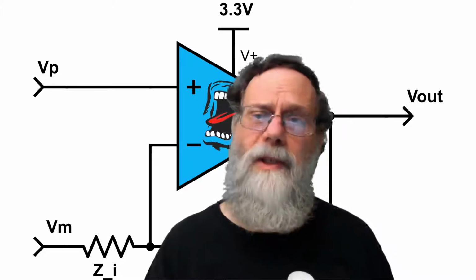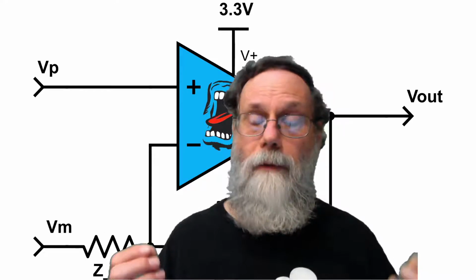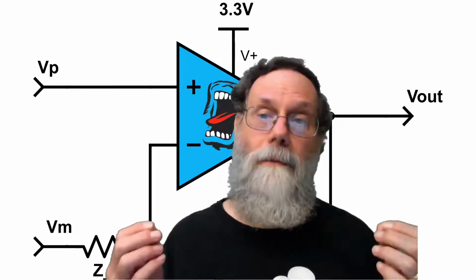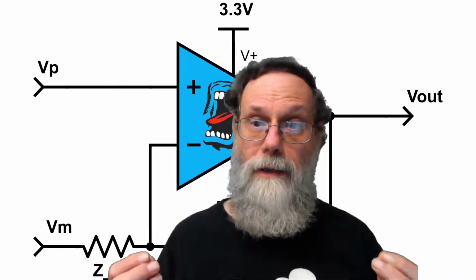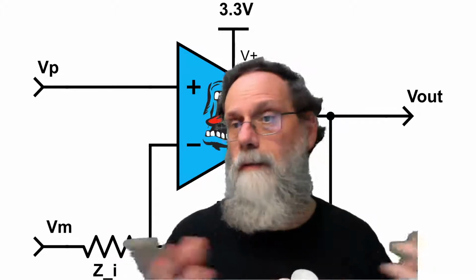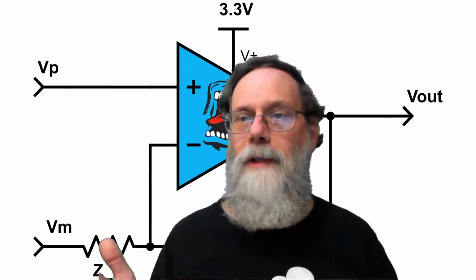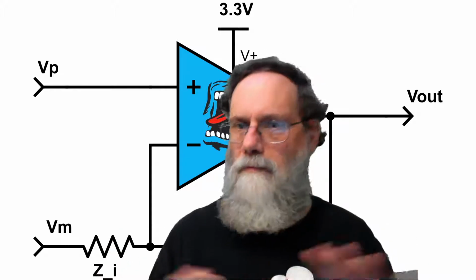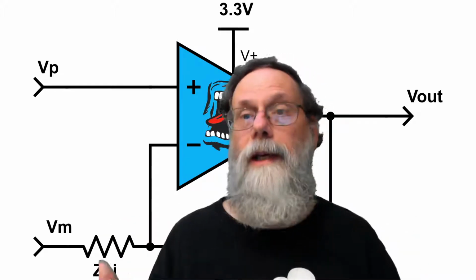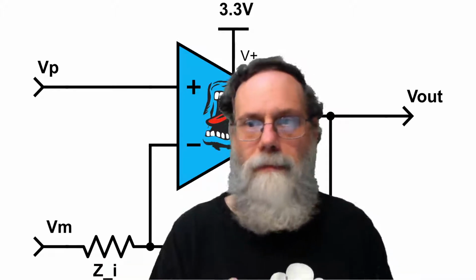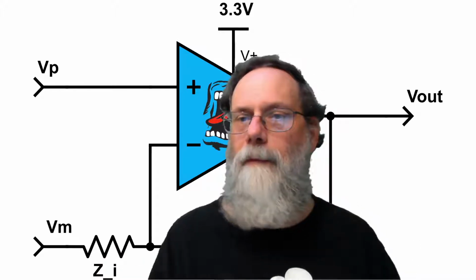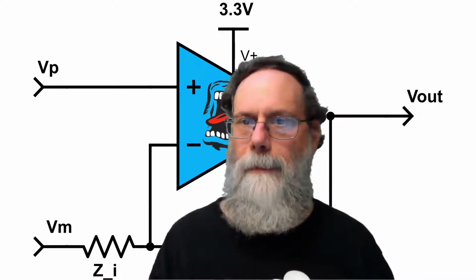So, a simple example. We can have a piece of wire. Now, a piece of wire can be modeled in many different ways. The simplest wire is to say, well, this is a metal, it's conducting, and every part of this piece of wire is at the same voltage. It's just what's called a node in electrical design. It's just one thing, and it's all the same voltage. There's no difference from one end of the wire to the other.